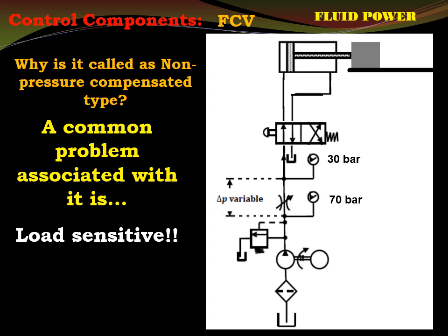Okay, what is the pressure difference across the orifice? 40 bar. Okay, so we can find out Q through it. From that equation where del P was one function, we can put del P there. A0, the area of the orifice, is also there.